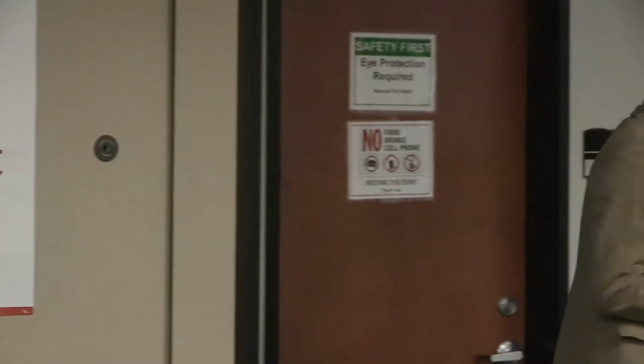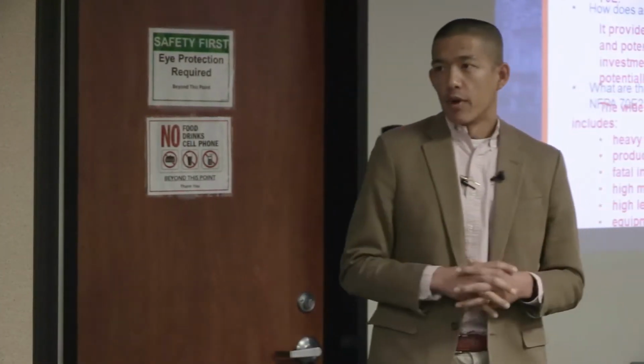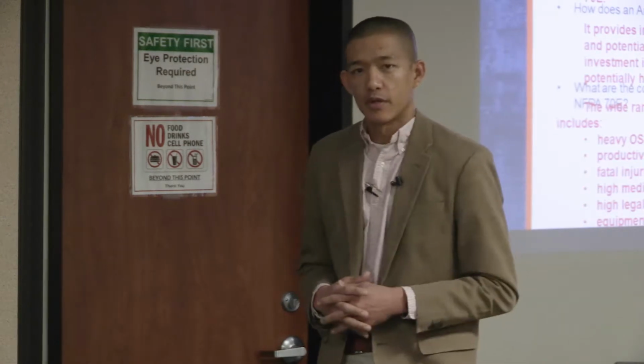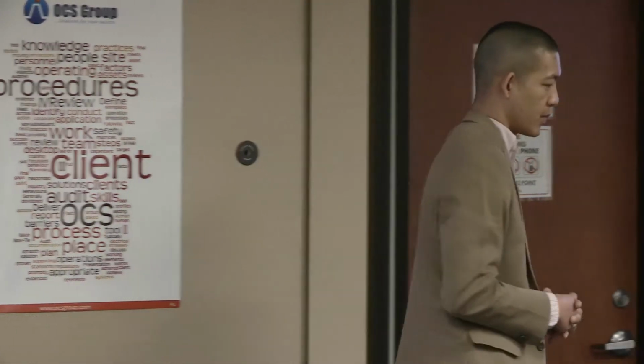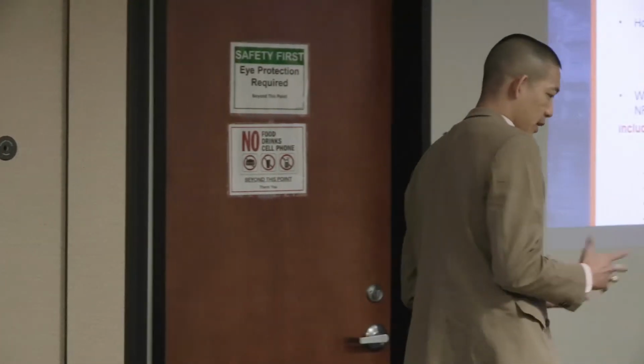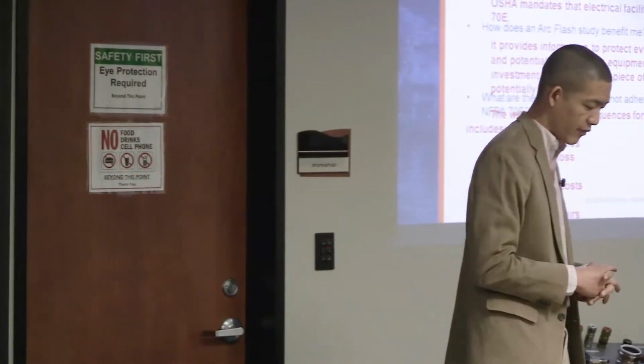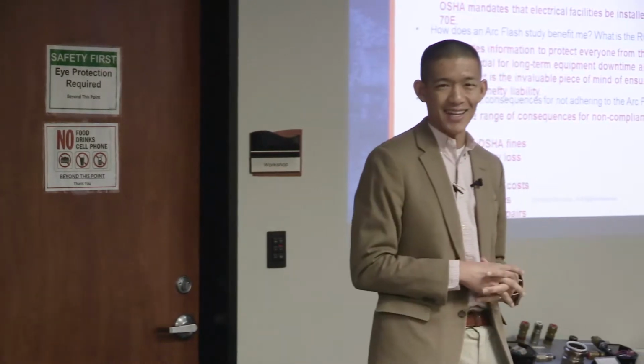And we also take into account the loads, the motor sizes. One thing that we always do is we model all the motor loads in the system, and that's because whenever there's a fault in the system, all the motors that you have in the system are actually acting as generators. So all those motors are contributing back to that fault current. So that's something that you want to keep in mind if anybody ever does perform a study for you, that they're modeling it to that level of detail.